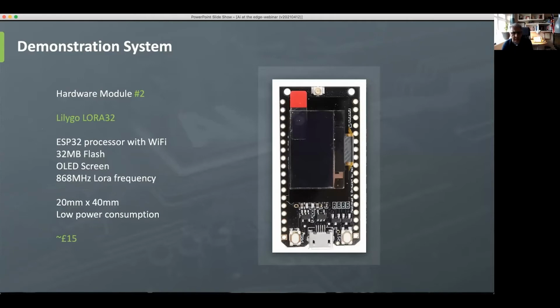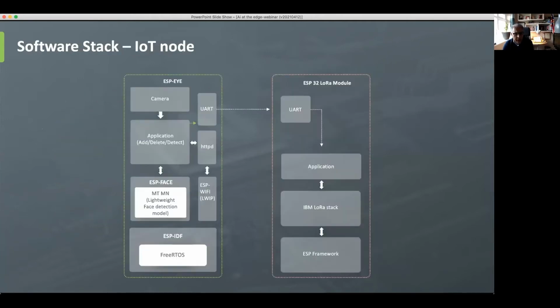And just very quickly, chaps, you've mentioned the wireless connection there, the LoRa network. I don't know if you covered that a second ago, but is that free? Is it a licensed kind of bandwidth? Okay, so it uses license-free frequencies. We are piggybacked onto a thing called the Things Network, which is a worldwide LoRa network. There's a worldwide network of gateways which feed into their network. That is free. There are paid-for versions.